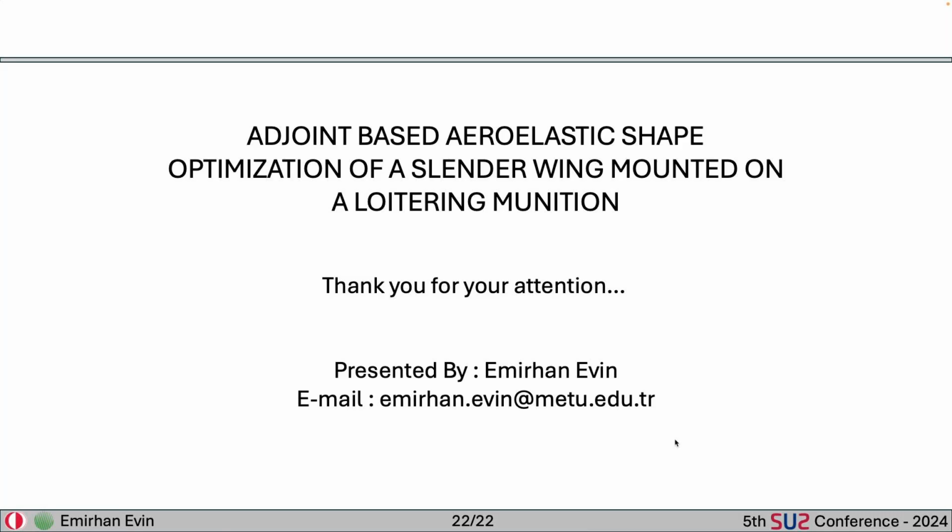Okay, so when you showed the surface mesh for the blade, I think at the leading edge it was all isotropic triangles. Is that needed by the deformation or the FSI? I don't think it's really needed for the FSI deformation. I just used unstructured mesh for all the domains and surfaces.